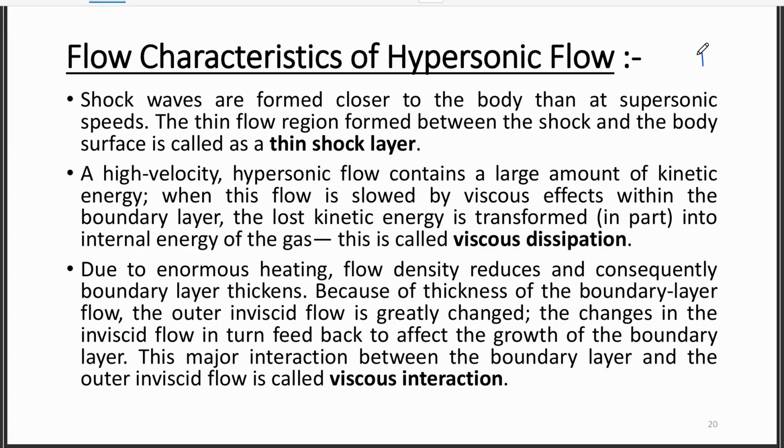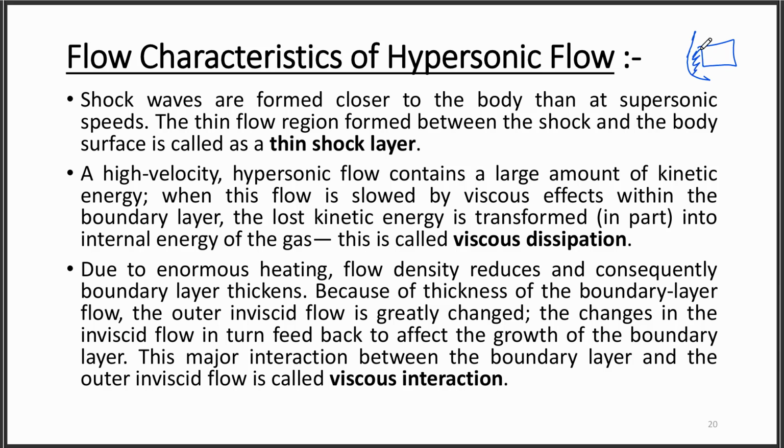Let's say there is one body and there is a shock around it. The region between the body and the shock is called the shock layer. In hypersonic flow, this shock wave will move closer to the body compared to supersonic flow, due to which there will be a thin flow region between the shock and body surface, which is the thin shock layer.